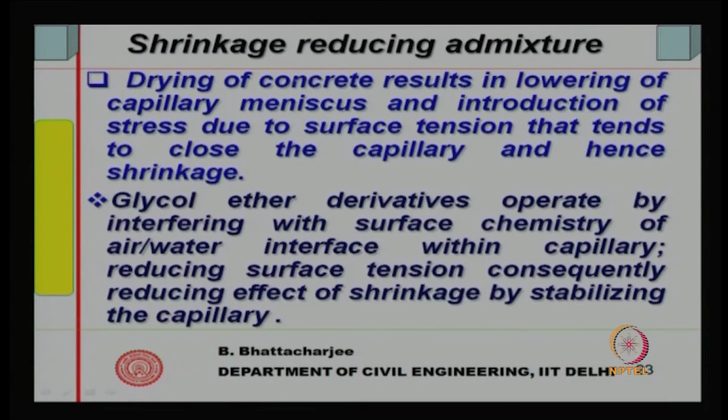So, shrinkage does occur, and then of course, gel pores will also become empty. The water will move out from the gel pores subsequently, and there could be shrinkage of concrete. So, with drying there is a shrinkage of paste and hence the concrete.